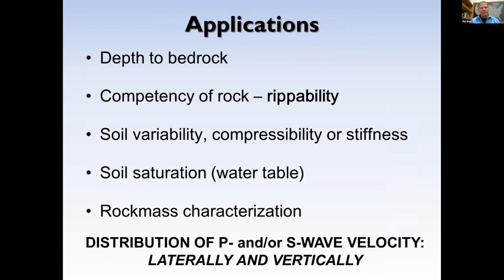So what are the applications of refraction? The probably biggest one is depth to bedrock and competency of that rock, rippability. I know that CalTrans is going to show applications of those, and our soil variability, compressibility, and the stiffness of it that we can get out of it. Soil saturation, earlier Dr. Wood showed an example where he was trying to get that out of his seismic data, and often we can in the right soil types. Or rock mass characterization if all you have is a hard rock site. But by getting that lateral and vertical distribution of P and S waves, that's the real key of what these are showing you.